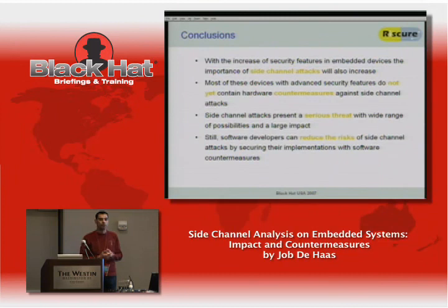So developers and implementers need to start thinking about these implications and also start to look at their development techniques, to see in how far they need to implement better library routines, for instance for comparisons, DES implementations or RSA implementations that implement blinding, etc. You can see that actually doing this does make it more difficult. It may not prevent it, but it may be the difference between a very simple attack that someone at home can do and an attack that an advanced attacker needs a couple of weeks of analysis for. And that's actually the level that you want to get to, often in these cases.